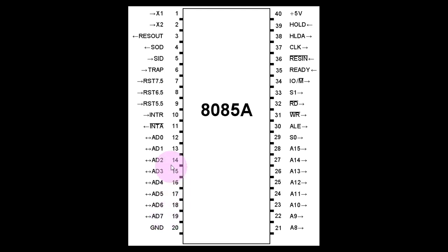So this address bus is connected from AD0 to AD15. This external memory will be interfaced to this microprocessor through this particular module. If you want to interface that memory directly, these pins can be used. If the external memory is interfaced and you write a program, it will be fetched inside the instruction register, given to the instruction decoding unit and the timing and control unit, and everything will start to execute.